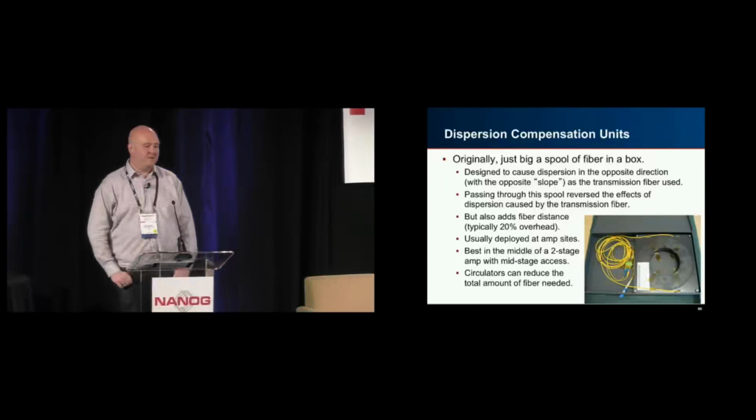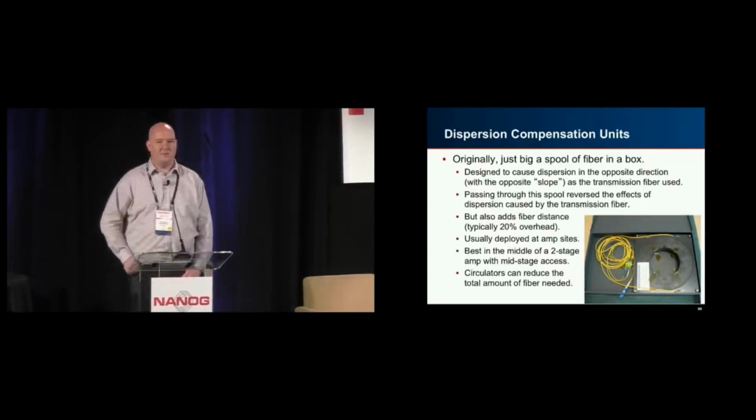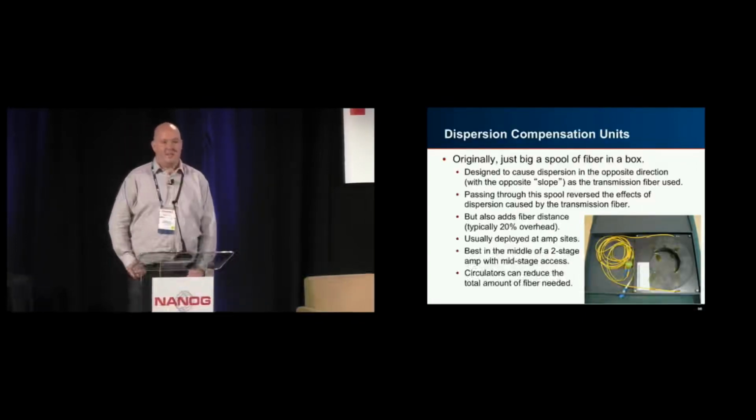Eventually it moved to being done with Bragg gratings, so you don't need an actual spool of fiber, because the spools of fiber introduce latency and people don't like those. Historically, it added like 20% overhead. So when you had these old spool-based systems, it added a significant amount of latency to the system.